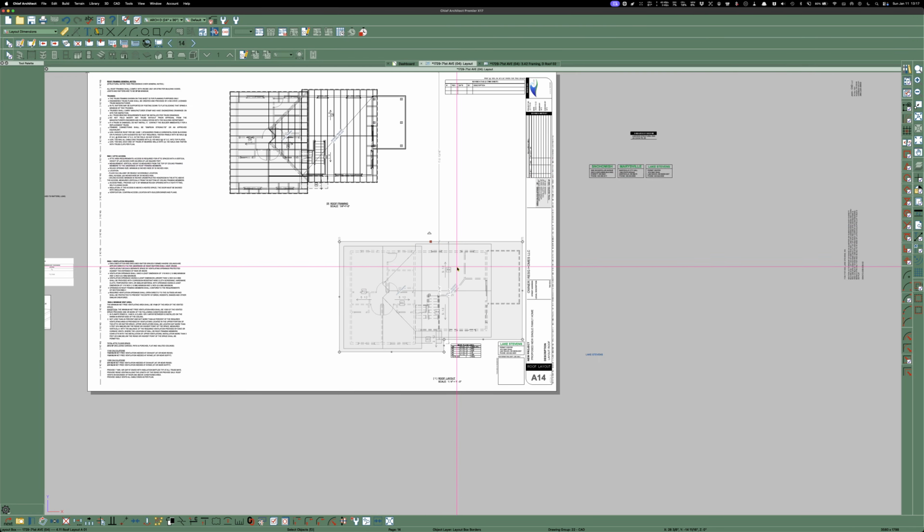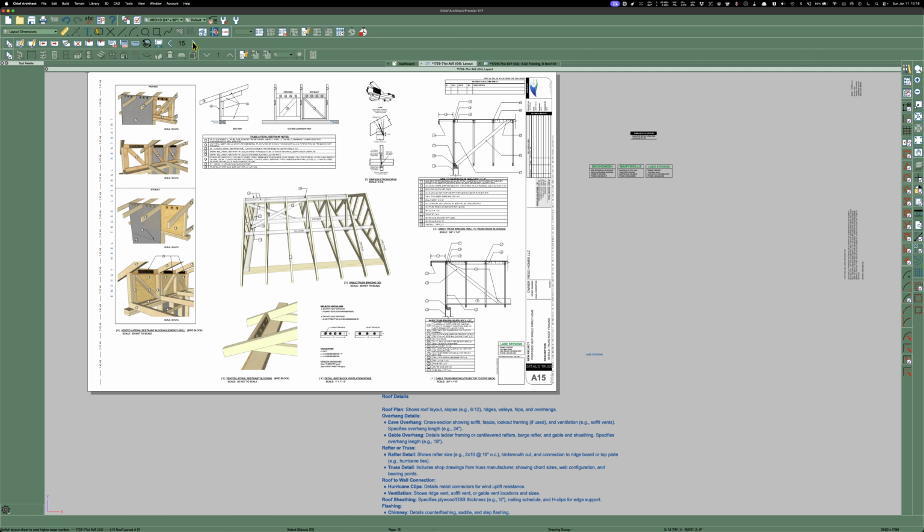But the trick to this is this allows you to have one model and turn off or turn on different layers and save them as saved plan views. And then you can put them on your sheet wherever you want them. Now this is all, like none of this came from the model. I drew all this, and these nice colorful ones, that's why I use SketchUp.